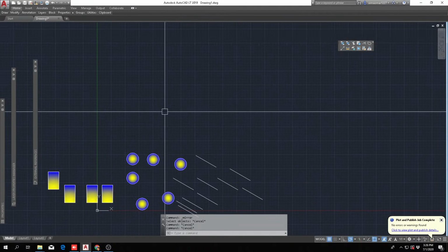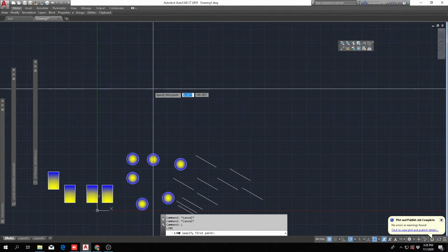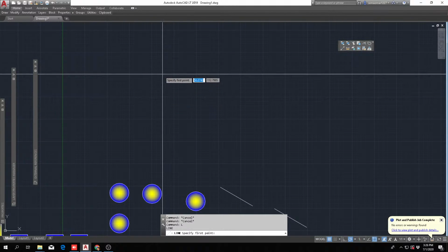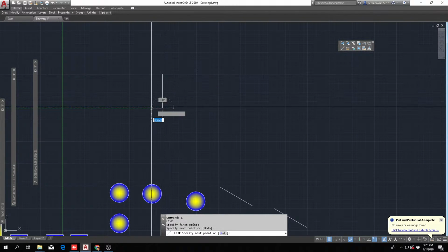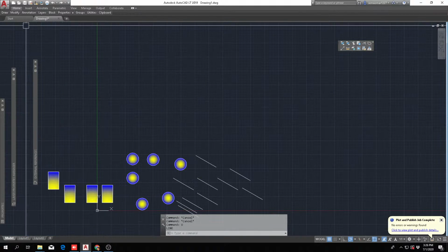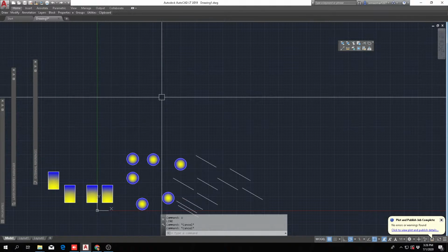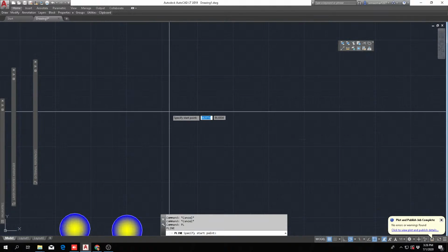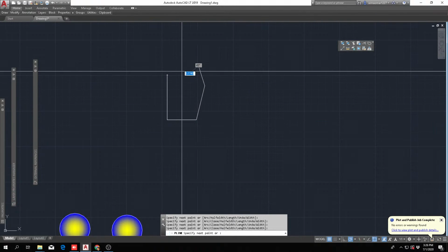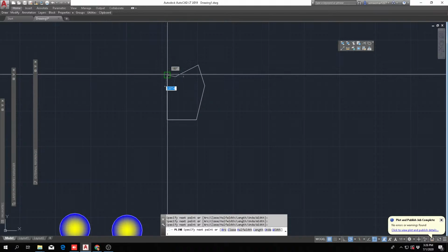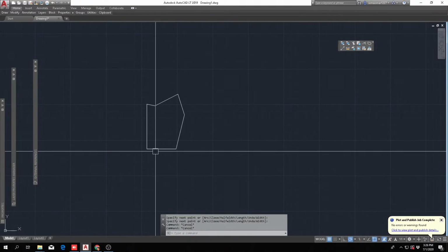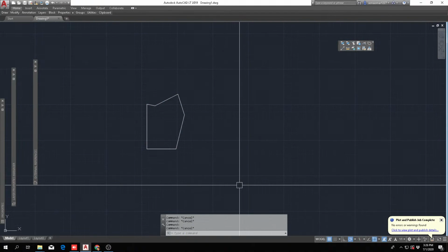Before we do that, let's go ahead and draw. Go to L, enter. Let's just draw something. Okay, undo. Let's use our P line command, since you already know how to do that. PL, enter, and do whatever figure you want. Doesn't matter. Just make a little thing like that. Okay, P line. All lines are together.